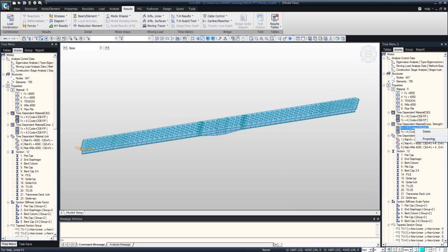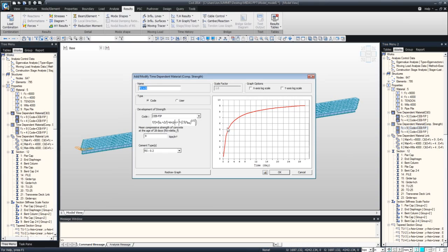We go over to the compressive strength. Just one short note here, this is where I was mentioning earlier that we like to always have at least 3 days of age on the element before we construct it for the most accuracy. If we forget and construct an element at day 0 and do any amount of loading, the behavior is very unpredictable and excessive just because the strength hasn't reached what it needs to from the time-dependent curve. Once we get to 7 or 10 days, it's high enough that it becomes fairly accurate.